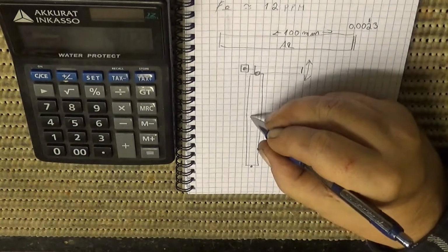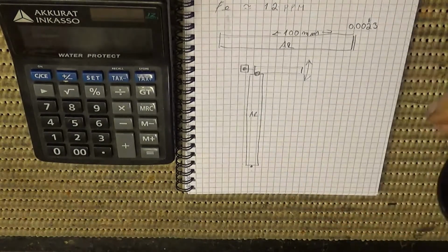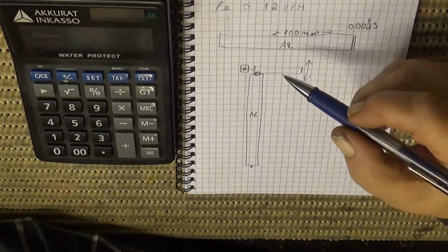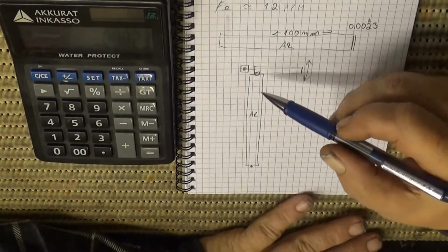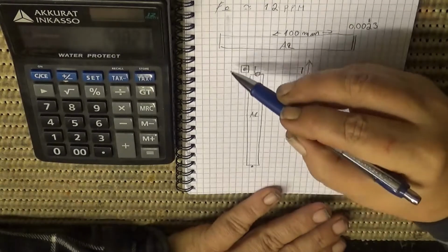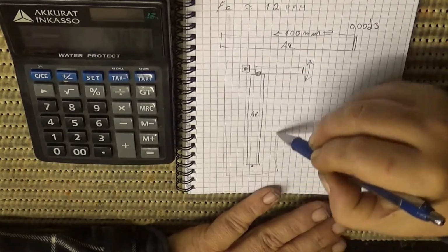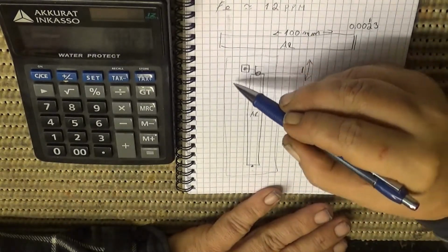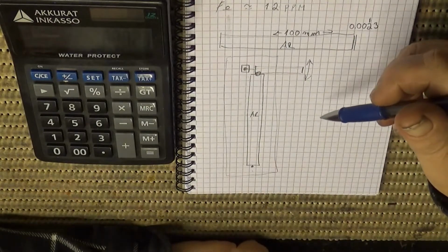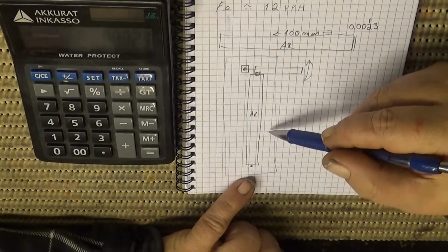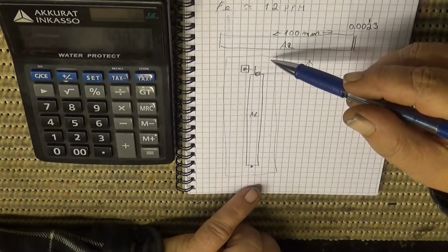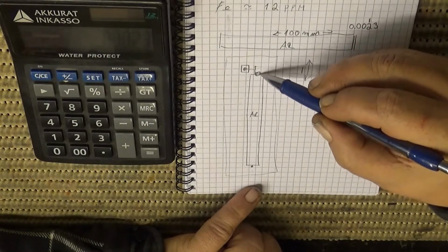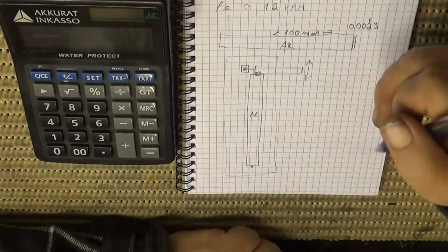Okay, let's say this is aluminium. So if we put some plate behind here, which is also aluminium, the plate also becomes larger with the temperature, and there will be no change in here. It compensates itself.